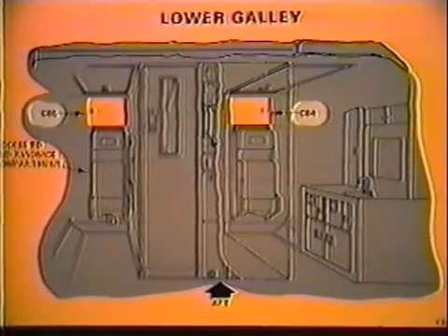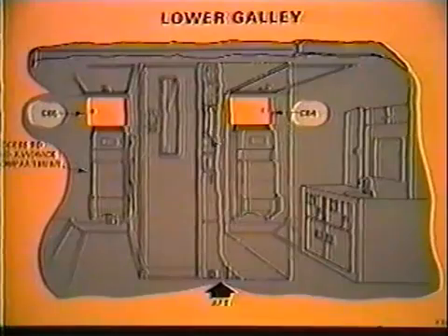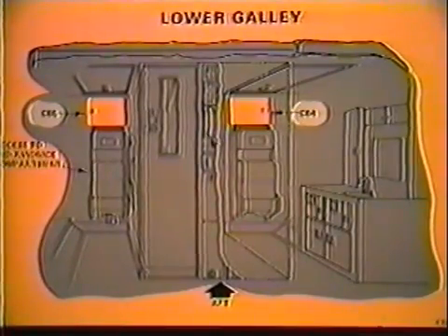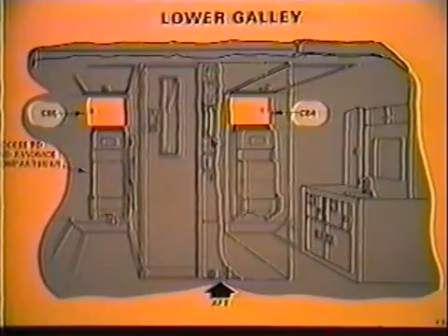This is a view of the lower galley looking aft. Above each folding attendant seat is a galley circuit breaker panel. Items found on these panels are basically for cabin and galley equipment. The seat on the left lifts up, providing in-flight access to the mid-avionics compartment.